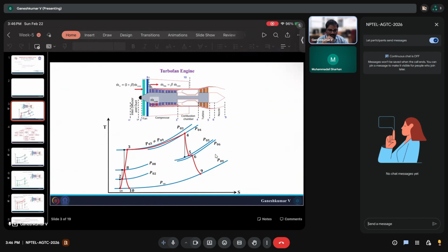Okay, I understand. So the core is very near. Whatever air enters nearby the core will enter the core engine, and whatever air is going through the outer portion of the fan will go to the bypass. Those are very minor pressure differences, so you need not worry. Across the fan, the pressure is going to rise, and after that the air stream is divided into two at the same pressure. Whatever the compressor sees is the same as whatever exited the fan. Does that clear it up?